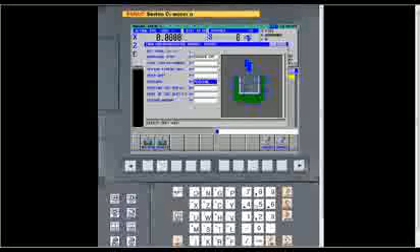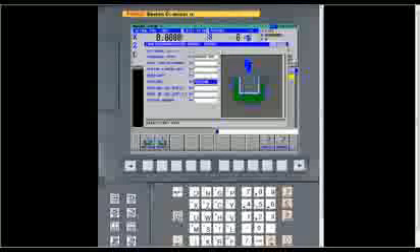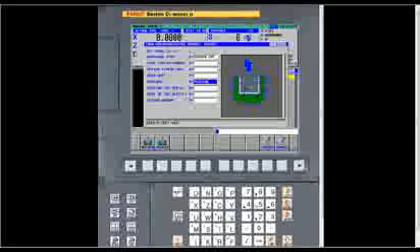A feed rate, a pecking. You can tell it to peck, where it just goes in so far, backs out, for where it will break a chip. This is very handy for grooving because we've all been down that road where we do a grooving cycle and we end up with a chip that's about 3 miles long. We don't want that. This is very powerful. It gives you a choice of where you can get around that.